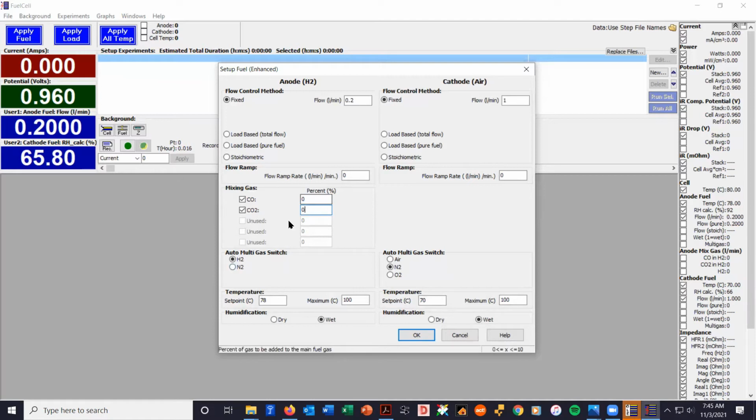And you can have mass flow controllers on both anode and cathode, right? For an 850, you can have up to 3 additional mass flow controllers if there are 2 mass flow controllers internal. So just think an 850 can have 5 mass flow controllers operating at one time. That's how many it can control: 2 internal typically, and then 3 external. That's typical. If you're working with an 890, it's more. I believe it's 7 mass flow controllers in total.